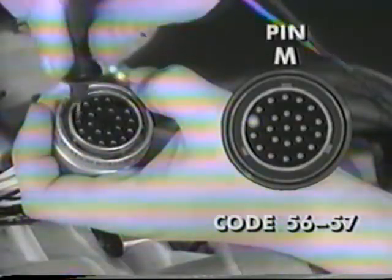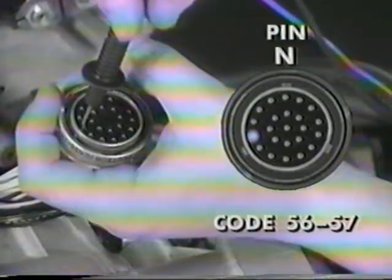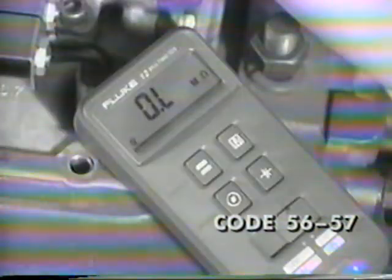Since our readings are good, next we probe between vehicle electrical ground and pin M for code 56 or N for code 57. The volt-ohmmeter should show an open circuit. If the readings on the auto shifter harness are all okay, replace the shift bar cover.